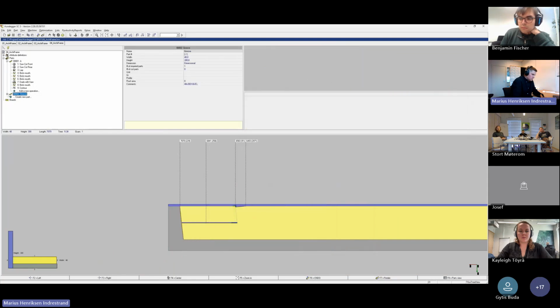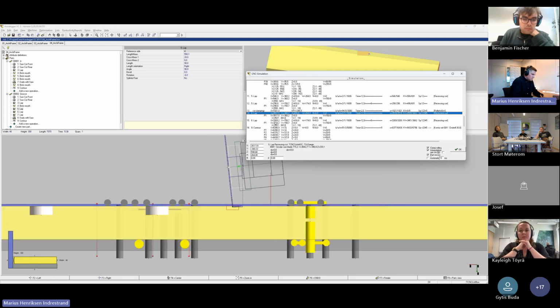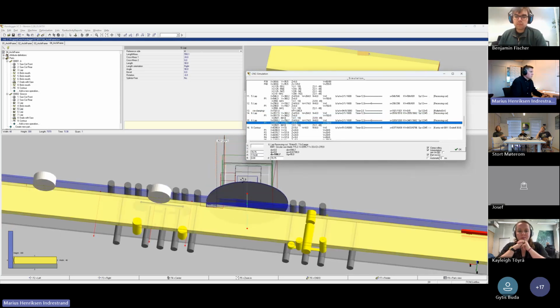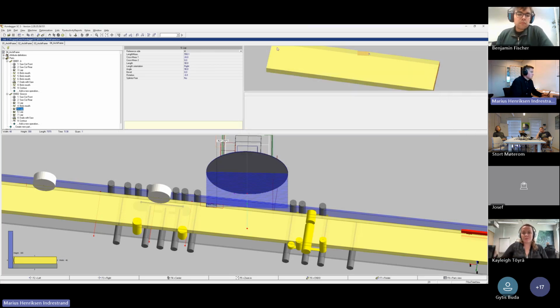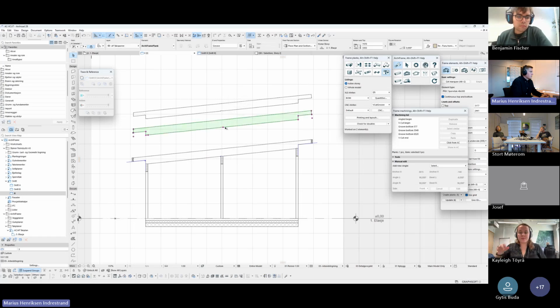But if you use the groove tool, there will be a lap. It will just jump down, and then it will use the saw blade to cut this incision instead of using the revolver. So that's something you probably should talk to the guys operating the Hundegger about, or if you have some rule about this, depending on which tool you want to use in ArchiFrame. It's longer, but for us, we like to use the groove.